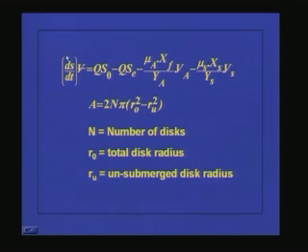So your final equation will come like this: ds by dt in the total reactor is equal to Q into S0, that is coming in, minus Q into Se, this is going out, minus mu a into Xf by Ya into Va minus mu s into Xs by Ys into Vs. So this is the substrate utilized by the attached growth system and the substrate utilized by the suspended growth system. And now we will find out what is the Va.